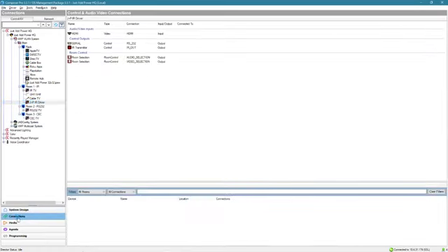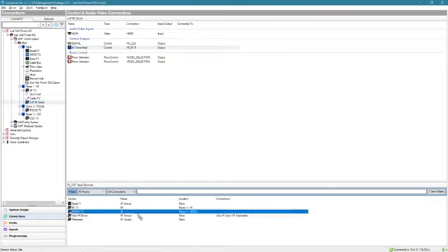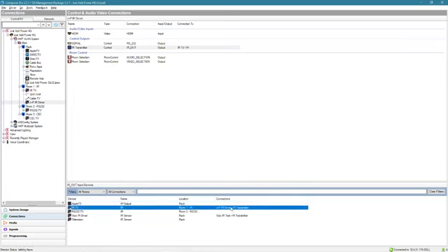The second thing we're doing is we're going to connections. And on this, there is an IR transmitter, and we're going to connect it to the IR TV's IR receiver. Now, when Control4 goes to send IR commands to that television, it's not going to use an IR port on the Control4 processor. It's going to send that off to the Just Add Power receiver through the IR port on the Just Add Power device to the television.